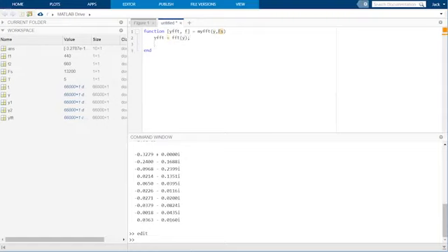Next, we can throw away part of the FFT result that we do not need. As we saw in the lecture slides, for a real-valued signal with n data points, we need the ceiling of (n plus 1) divided by 2 cosines. But the FFT returns a result that has n data points. Why is that? The reason is that the FFT function works for both real-valued and complex-valued signal inputs.